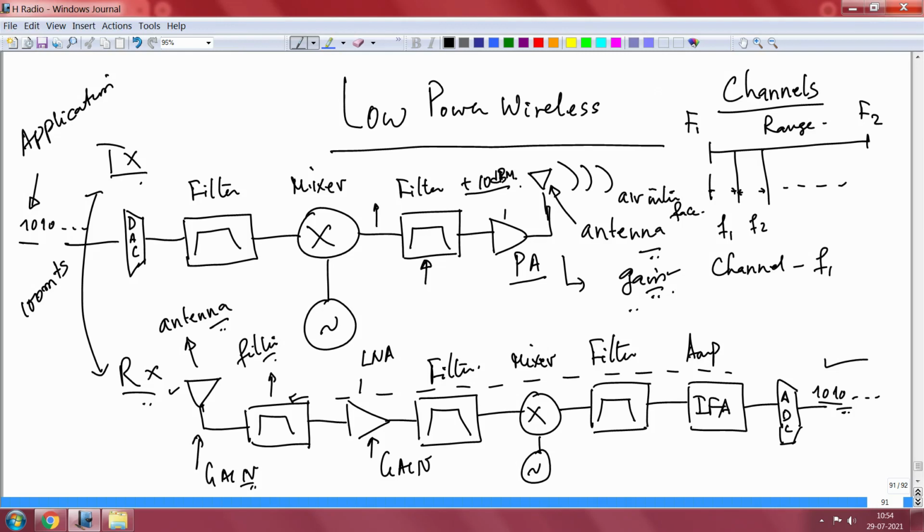That is why this discussion is important. What you do with BLE in terms of the transmission at the physical layer can be different from what you do at that layer for ZigBee. It will be just one more block that you will have to add in somewhere in order to ensure that it does direct sequence spread spectrum modulation as compared to BLE doing something else. But broadly the chain remains the same with minor modifications. Therefore, by software you can say I am going to remove this block, I am not going to energize this block, I will energize the other block.